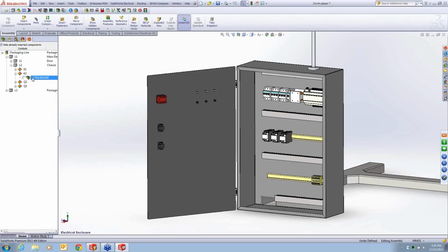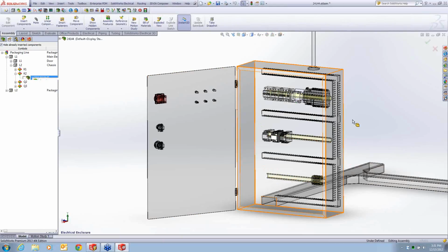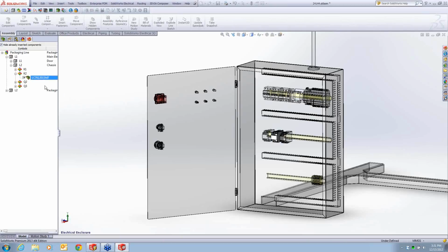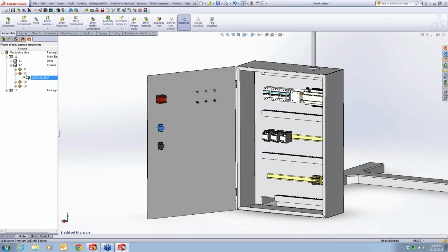Now if I find something I want to insert, I can insert it into the tool, and I can align it using snap-tos and SmartMates, or I can associate it with something if I've already placed that CAD geometry in the tool. So I simply would come in and say associate, and you see how my drawing has changed. Basically, it's telling me what components I have in the 3D model that have not been assigned to something. In this case, there's only one thing that's left for me to assign it to. Go ahead and select on that. Click OK, and now that's been assigned to a component.